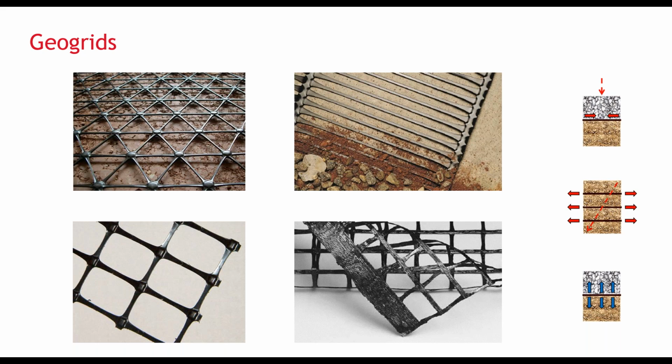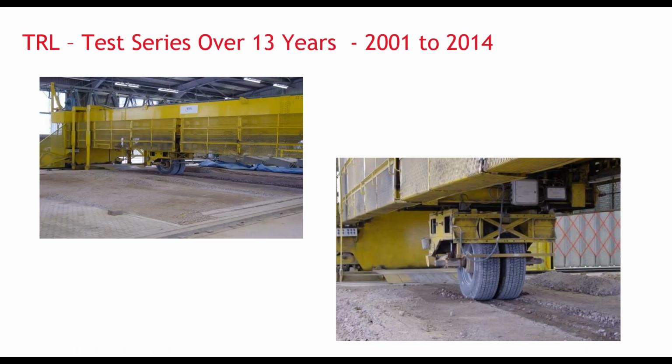All design methods for geosynthetics and road applications developed to date are based on empirical testing. The nature of these applications and their construction, along with the natural variability of materials such as soil, aggregate, and asphalt, make it impossible to accurately determine performance based on the materials themselves. This is why it's impossible to correlate specific material properties, such as tensile strength, with performance in a road. Instead, we rely on full-scale moving wheel tests, which generate large quantities of data that allow us to analyze performance probabilistically. We'll see in a few moments how AASHTO design methods for pavement use this approach.